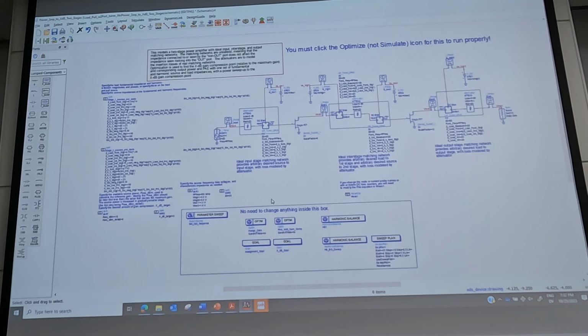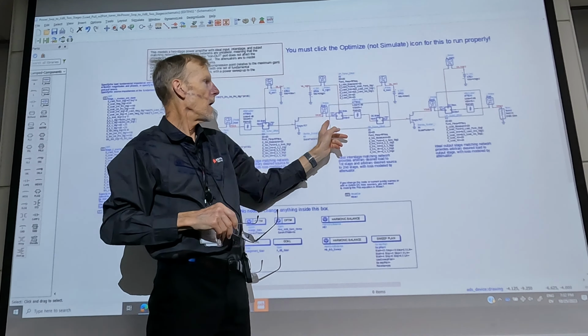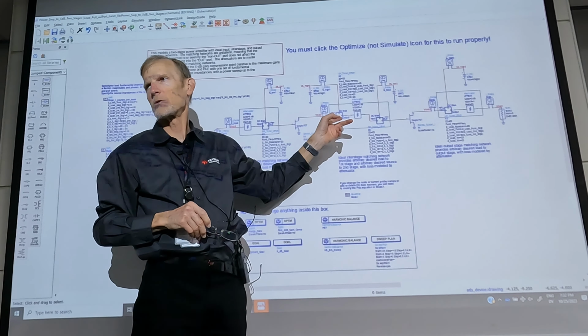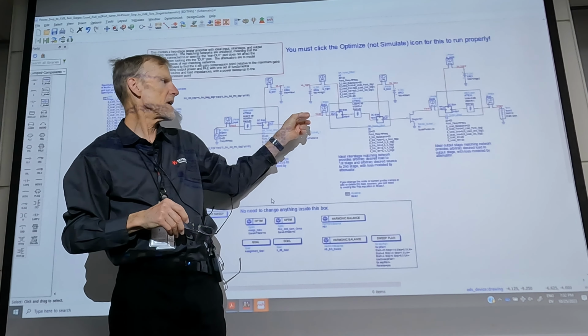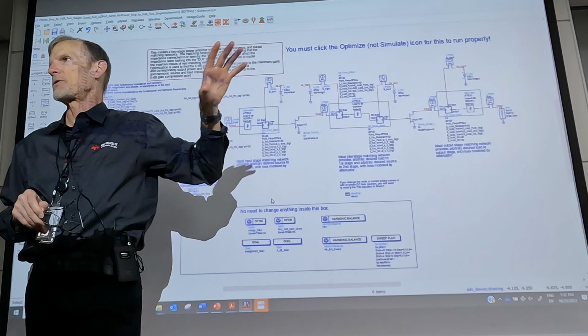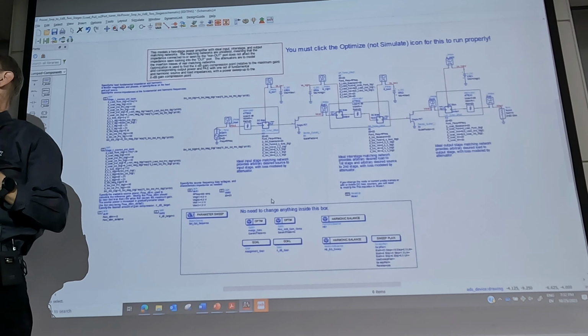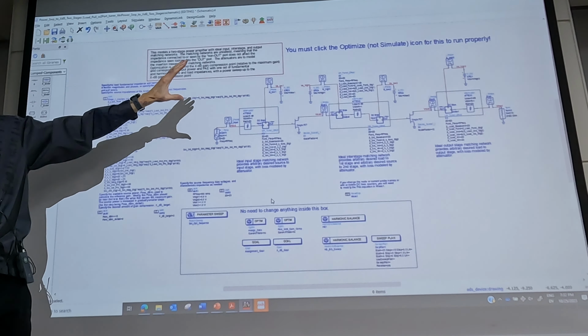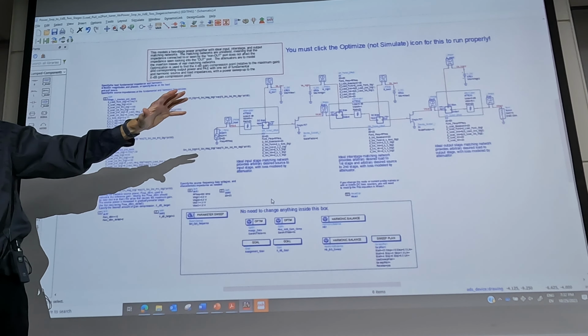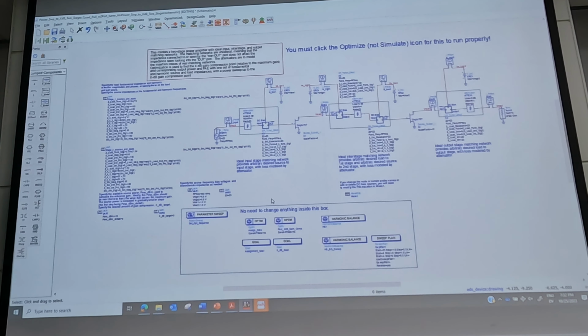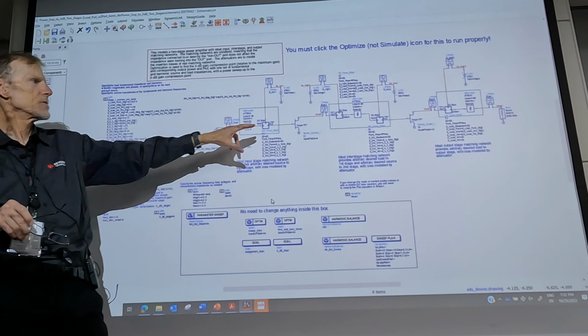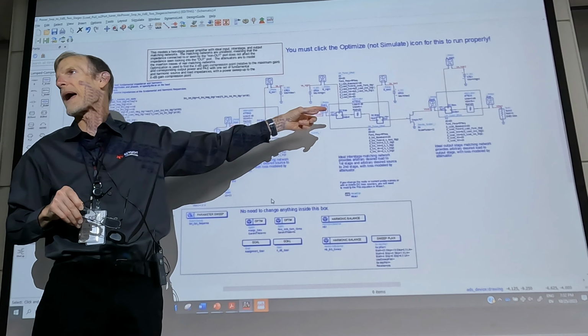So this is kind of like a maximum, best-case performance. You can't get this in reality because you probably cannot create a real interstage matching network that gives you the ideal conditions. But maybe this is useful as a tool to see the best case you could get from these transistors and from the load pull that you ran.